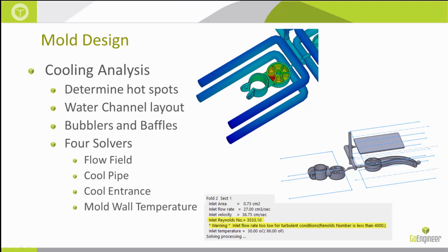When we set up a cooling analysis, there are 4 different solvers within SolidWorks Plastics. The first is the flow field, which is the highest priority. It's the most accurate, a fully 3D CFD approach. You can select multiple inlets and outlets, and it also looks for turbulent flow.